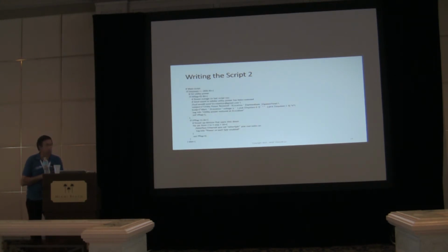And so here's our script. One thing with scripts is a hash means it's a comment. It's just a good idea to put comments there so you know what it is. So this is the main script. And this is where, if the voltage is greater than or equal to 26 volts, we do this, and the curly bracket is closed down here. There's a start and end. If you tab in and you keep track of where the curly starts and ends, you'll find it a lot easier. So this piece of code, this if loop, is that. This if loop is that.